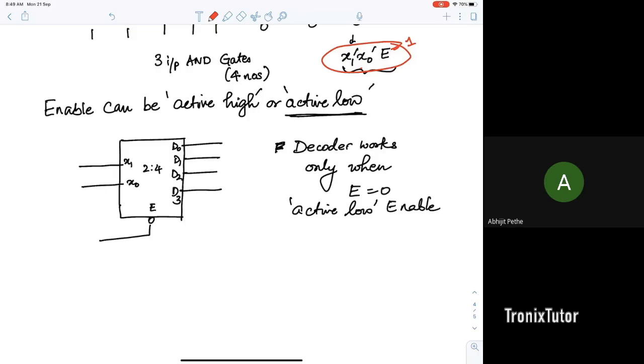Harsh, good question. In active low, if we are not using the chip most of the time, won't it waste more power, as we need to connect it to power all the time? That is very true. But what turns out normally is that, we'll talk about CMOS design towards the end of this week. CMOS design doesn't burn power when you have connected supply. CMOS design burns power only when you're switching. CMOS, which is the most common design technique, is normally a switching sensitive design. That is, CMOS will burn power only when we switch the circuit.